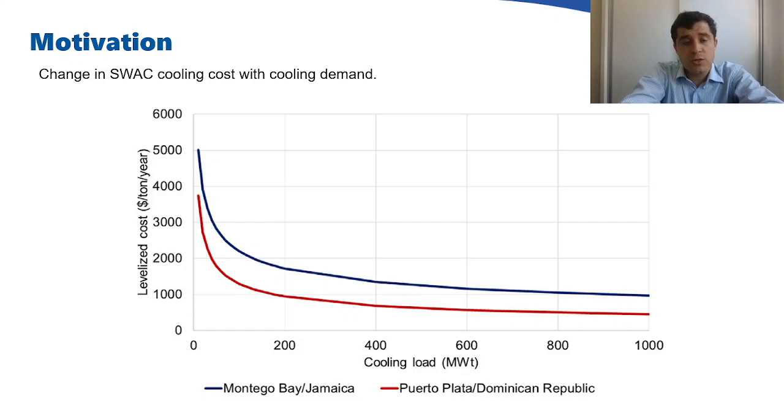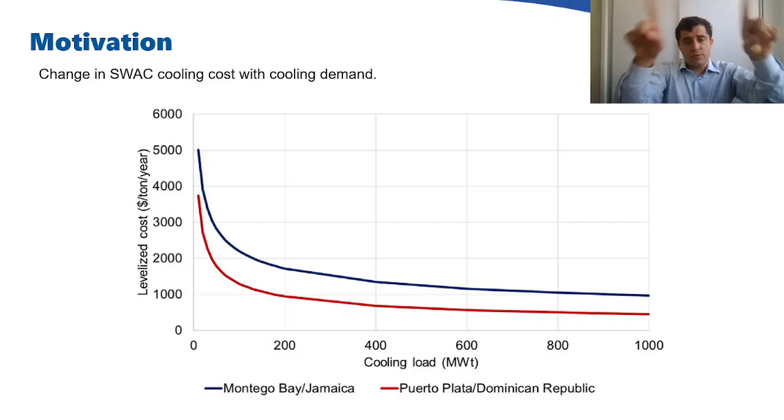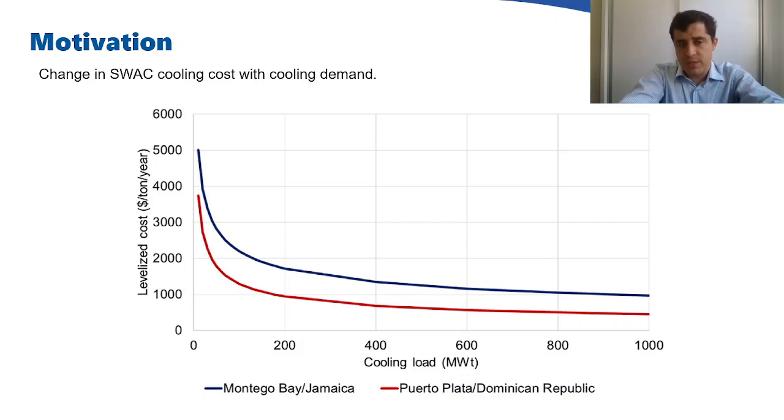One of the aspects I will focus on in this conference is the need to increase cooling demand, because the higher the cooling demand, the larger the pipes. If you double the diameter, you increase the flow area, the area for the seawater to flow in, four times. You reduce the friction, which increases the flow of water even more, five times, could be even six times higher.